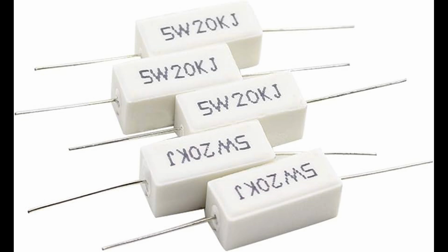It's important to choose the appropriate fusible resistor based on the specific requirements of your circuit, taking into account factors such as resistance value, power rating, and voltage rating. When a fusible resistor blows or opens due to overcurrent, it typically needs to be replaced with a new one to restore circuit functionality and protection.